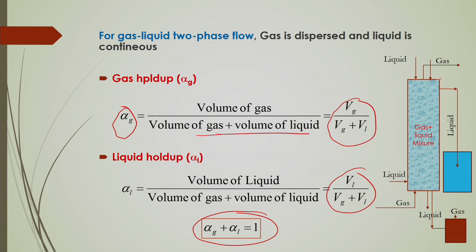So, that is for the three phase system. Here in this case if you consider this figure, if you consider that it is one column, you can consider it as counter current operation or co-current operation. If you consider co-current operation, from the bottom gas will be flowing and liquid also will be flowing. So, in that case the gas will be coming out at this outlet and the liquid will be coming out from this location. So, this will be a co-current upflow,